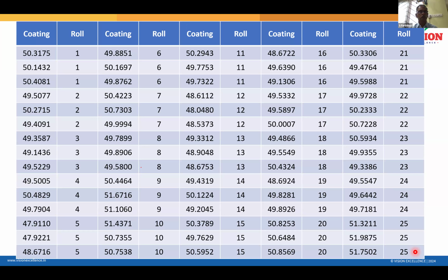And now comes the sample size. And for sample size, the guideline is always 2 to 25. What is the sample size followed here? 3. The sample size followed here is 3. Do you understand? But the range available is 2 to 25. And here the rule is more is better. Instead of 3 samples, you take 5 samples. Yes, that is a better scenario. But normally it is between 2 to 25.